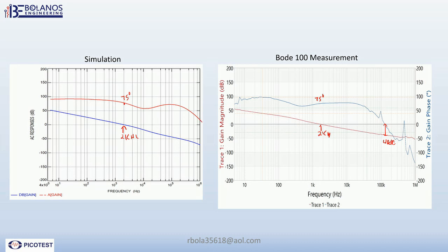Here it's a little bit off, but I'm okay with this because it's a simulation. I have a measurement, and the measurement backs my assessment that the power supply is stable. So this is the way you measure, and you get both simulation and measurement. With these two coming very close to an agreement, you can have confidence that your power supply is going to be stable.